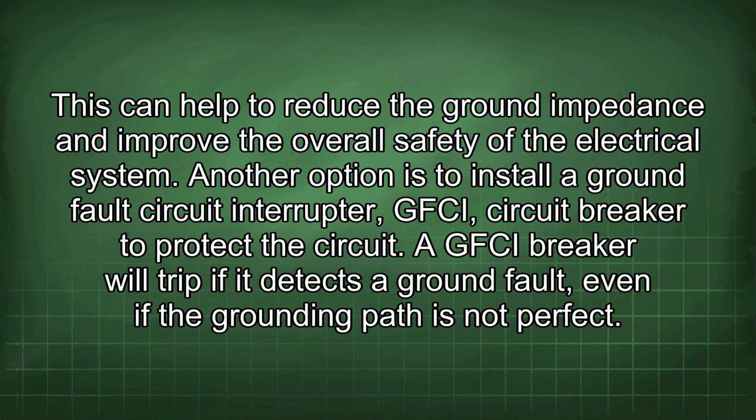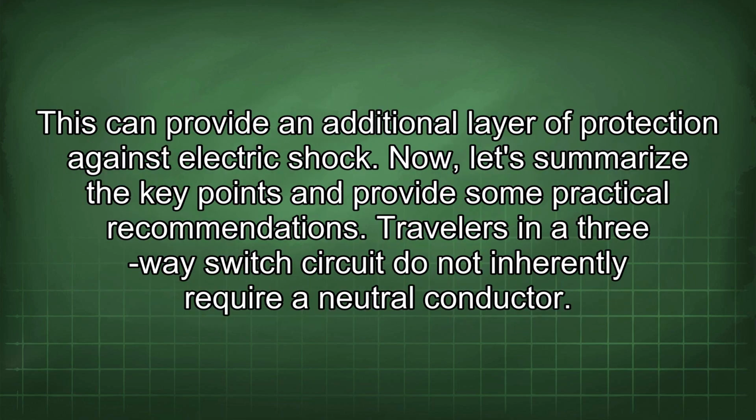Another option is to install a ground fault circuit interrupter, GFCI, circuit breaker to protect the circuits. A GFCI breaker will trip if it detects a ground fault, even if the grounding path is not perfect. This can provide an additional layer of protection against electric shock.